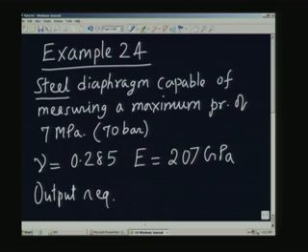this is the design requirement, is 2 millivolts per volt. This is the performance required at this particular pressure, 7 megapascals. Of course, when we are measuring a pressure like 7 megapascals, it does not matter whether we call it the gauge pressure, absolute pressure and so on, because the difference is very small. There is a very large pressure, gauge pressure, absolute pressure, there is not much of a difference in terms of its value.